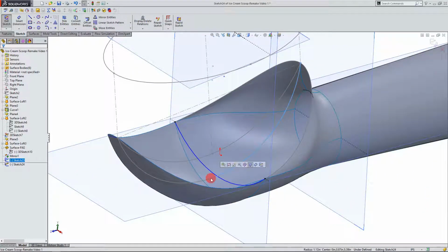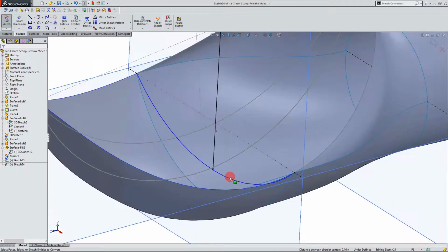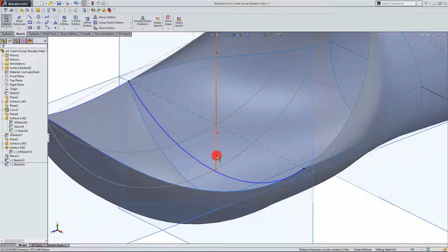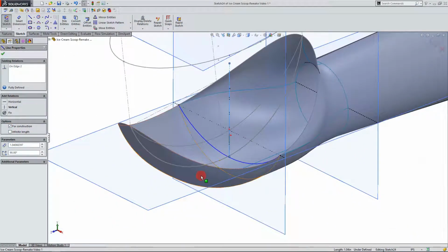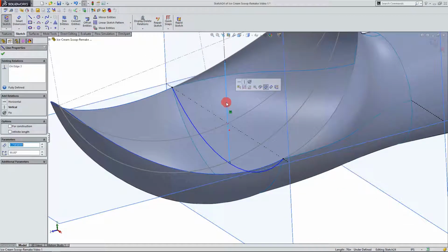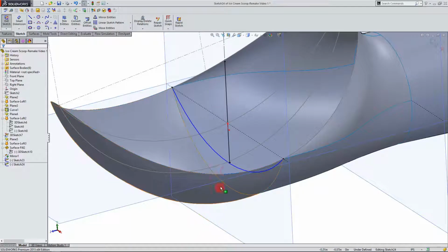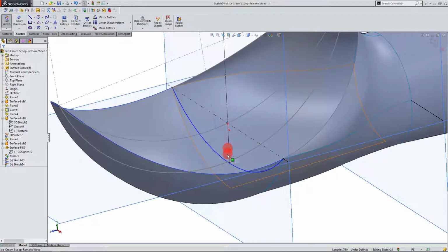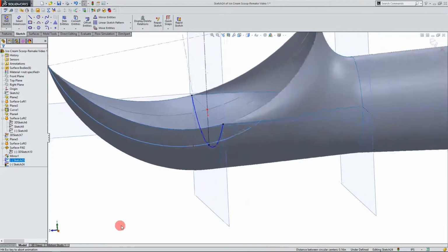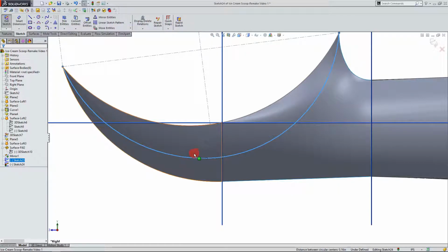And if I click on my two lines and convert them, I get a projection on this sketch. So I'm going to make this for construction. Just to show that again, in case I'm going too quickly, I clicked on both of these arcs on the sketch I just made, and I came up here and hit Convert Entities.